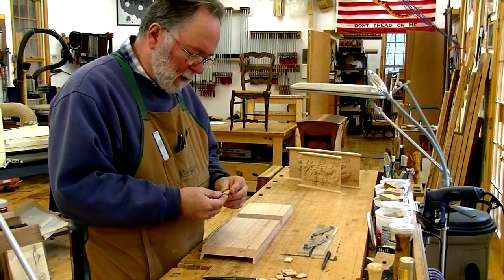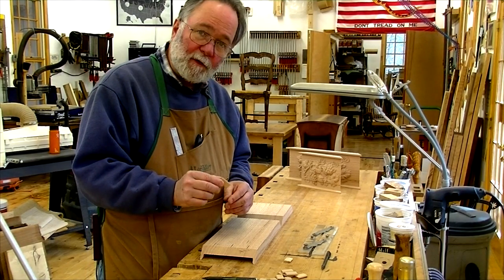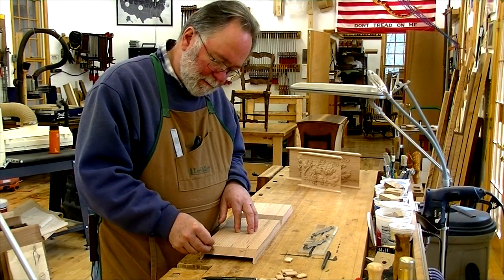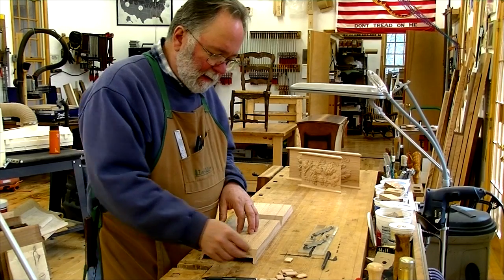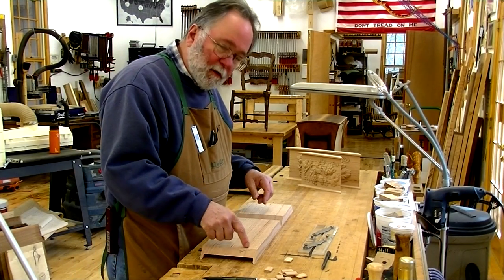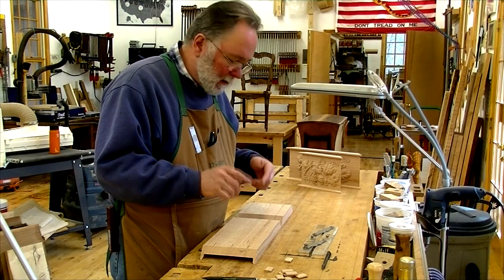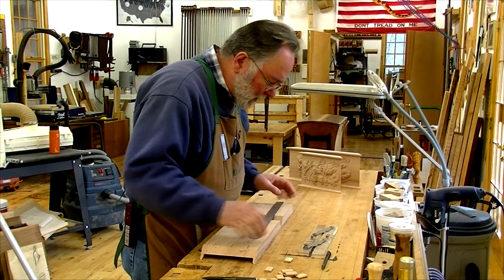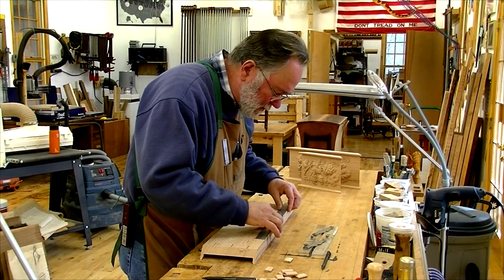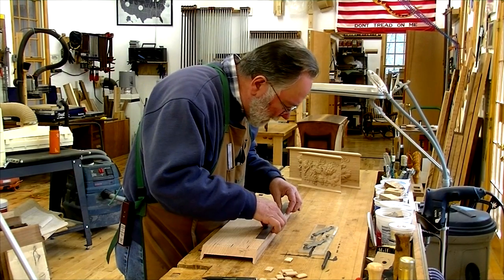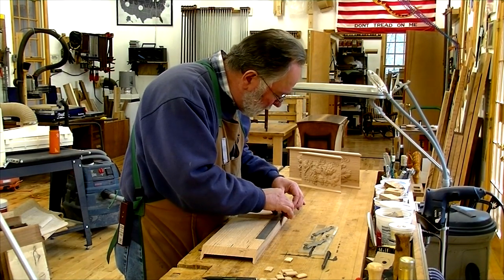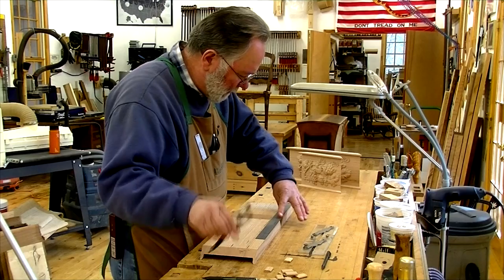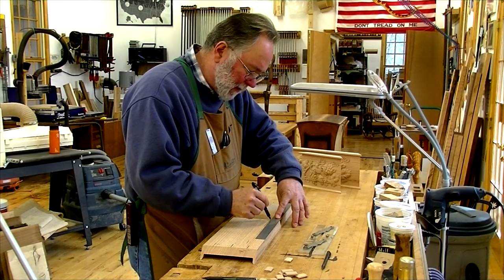I'm going to use these small 5 by 30 millimeter dominoes to hold the piece together, and I'll put 3 of these dominoes in each corner. And the trick is to get the lines for lining up the machine the same on both mating pieces. So what I decided to do was to just set these pieces together as closely as I could to the way they should be, and then use a ruler straight across the top and just scribe my lines.